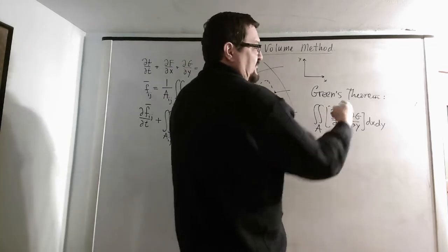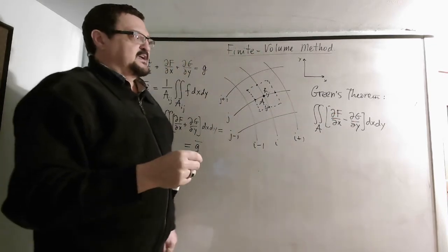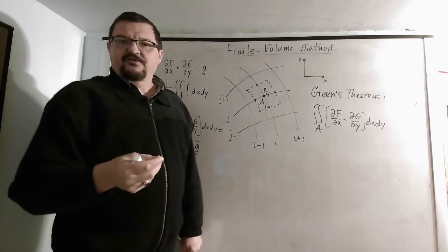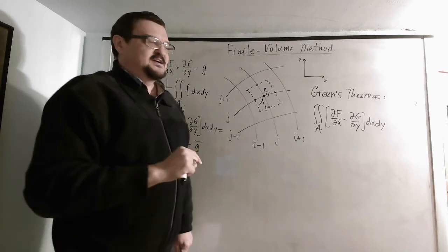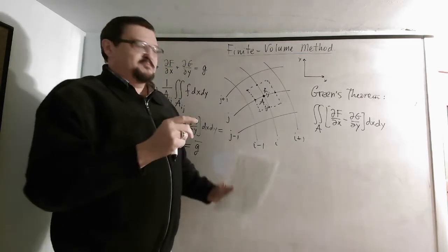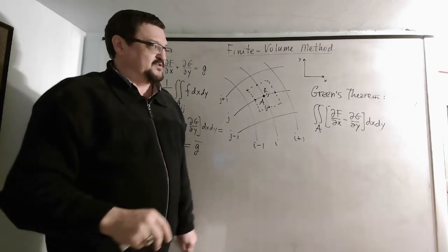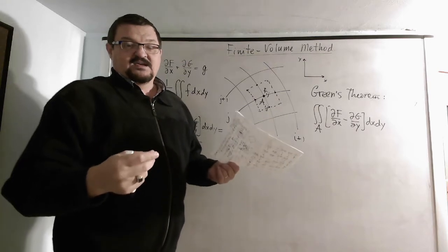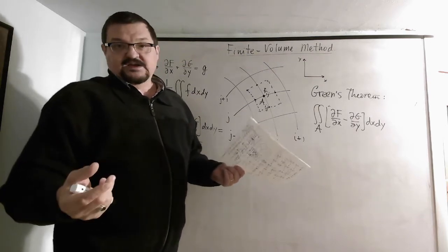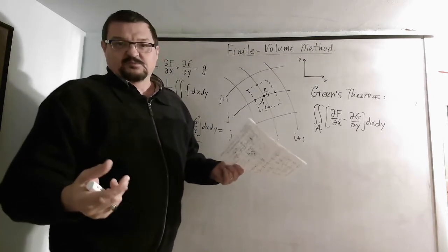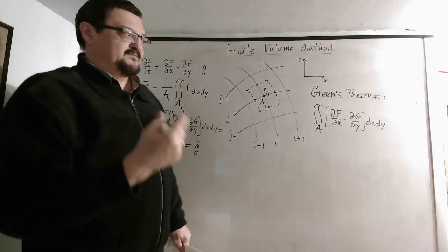So it's like the integral of vorticity, and this is not coincidental, because in Stokes theorem the left-hand side is an integral over volume, but of the curl of a vector. Curl is like vorticity: if f and g are velocity components, then it would be just vorticity. So it's the curl of some vector.